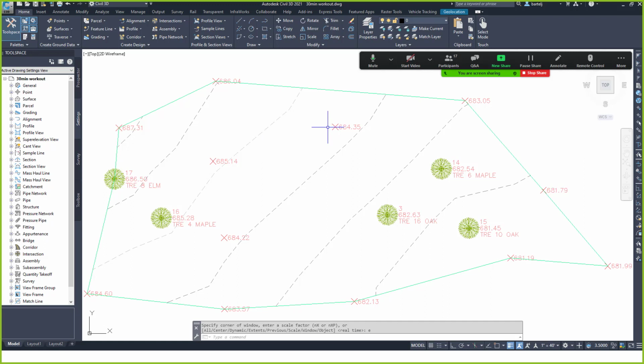All right, so like the first question, I start thinking, ooh, we've got objects that have dynamic relationships between things in Civil 3D. What does that do if I start freezing objects or freezing layers that control some of those objects? I've run a couple of examples, tests where if I froze points, did my surface want to update if the surface was built from those points, and it didn't impact it at all. That's not to say that it wouldn't impact any other variation between objects. I've not gone through an exhaustive test of that.